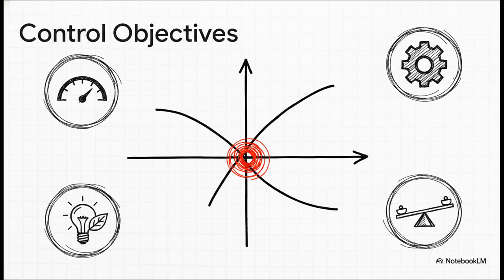Our actual real-world operating point is the exact spot where those 2 curves intersect. Think of it like a tug of war. If the motor produces more torque than the load requires, it accelerates. If it produces less, it decelerates. This push and pull continues until they perfectly balance out.